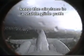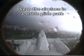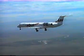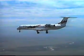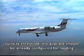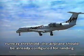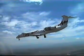Keep the airplane in a stable glide path, and remember that large changes in airspeed will require also proportionally large changes in power and attitude. Variations in the target airspeed must be kept within a range of 5 knots. Prior to reaching the outer marker, or at least 3 nautical miles away from the runway threshold, the airplane should already be configured for landing in a stable glide path with landing flaps and gear locked down.